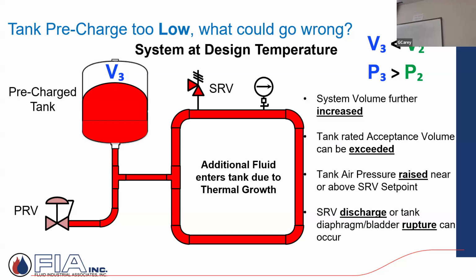Yeah, that's 2.3 feet of height per psi, right? So that's my pounds per square inch pressure. Especially the smaller residential ones, they only come at 12. The commercial ones are now coming at 40. But yeah, it's the static weight of the system water, so it depends on the height of the building.